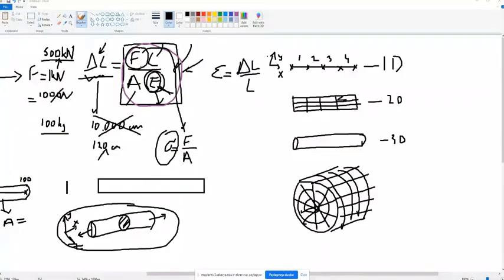So for the 1D element, there is no problem. All of them are just one line. For the 2D element, yes, these are rectangular meshes, but instead of this, maybe the automatic software will discretize the system like this. Triangles. But very simple models generally are not going to result with this. Simple models generally result with we call sweep, fine and sweep mesh.